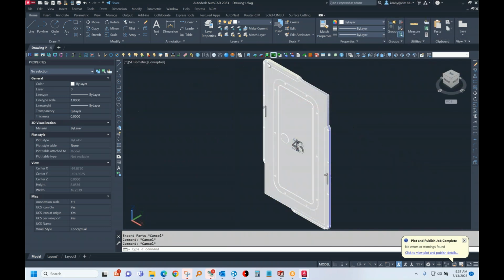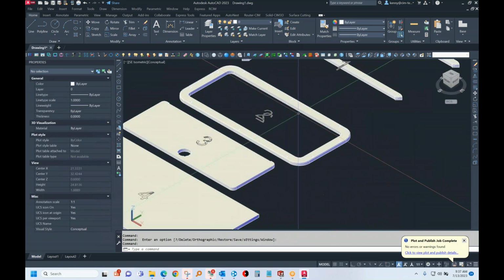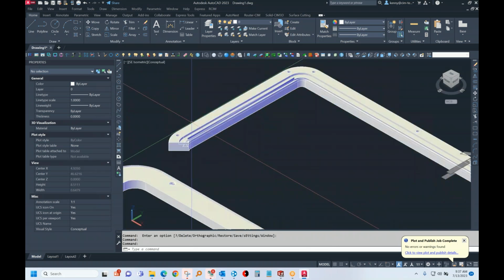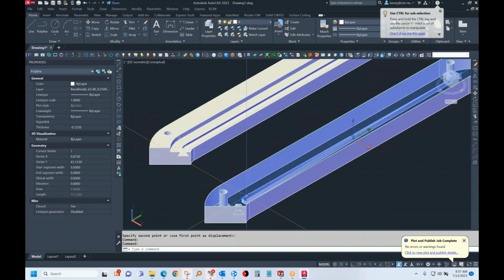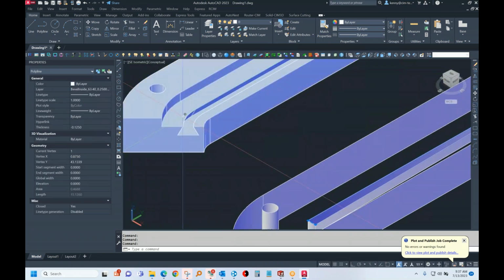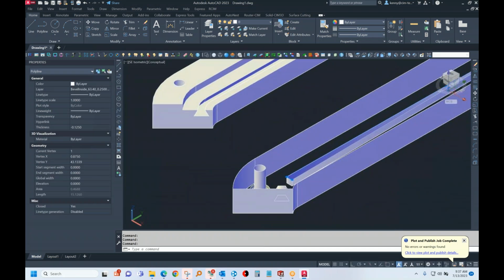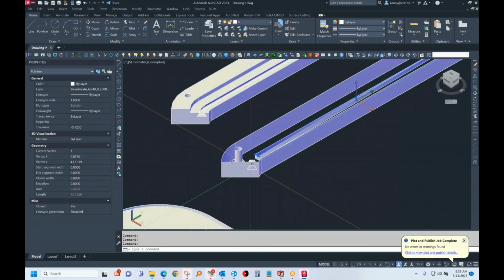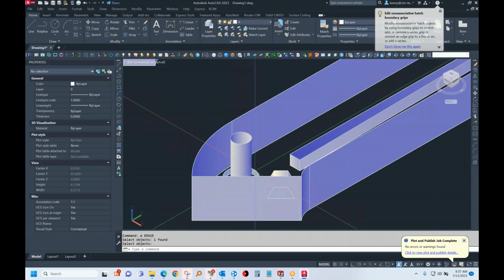It also can do a lay flat, so it can lay the parts out flat. And there you can see what kind of feature recognition you got. And on this part here, you could see, I moved the solid out of the way. We did not get perfect feature rec on this. See, it made a bevel inside out of this piece, and it did not connect this to this. And I suspect it's because there's some compound edge here that it just couldn't figure out. So we didn't get perfect rec on that, but we did get perfect rec on the counterbores and the countersinks.